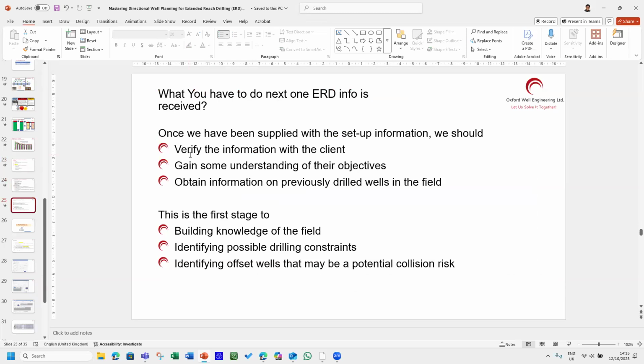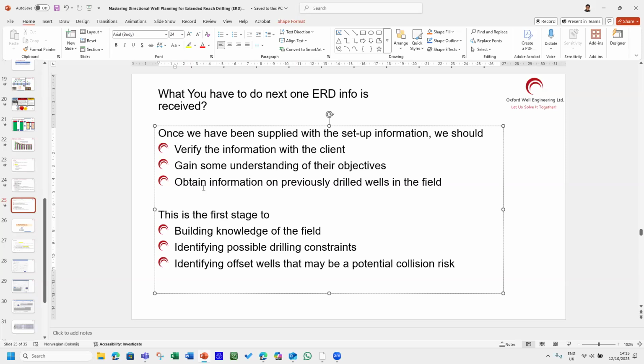what you should do. As I mentioned, verify. And also you will be creating the kickoffs, curves and bands. You say kickoff here, give me the dogleg of this, 3 degrees and 3.5 degrees, whatever you have in your mind. You just cannot come out with 3 degrees. In some places, a 3-degree dogleg is a big deal. You should know if they had a problem getting the 3-degree built. Then you say, okay, I will not put 3-degree. What they were easily able to build with, 2.5 degrees, 2 degrees, 1.5 degrees, whatever those are.